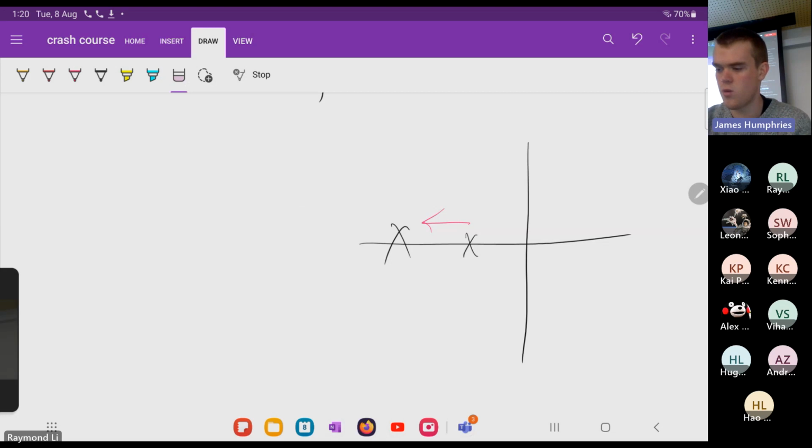Because if I go back to this, let's say I have a single pole. What happens as I increase the gain? It goes not to the right, it goes to the left. It'll go this way, and it'll eventually just keep going that way. Which is why, when we have two of them, we like to put the zero here, because then this one will go this way after this one gets there. They'll go that way for a bit, but it'll mainly end up going further to the left. Because we want to cancel out the dominant poles. We don't really want the dominant poles there, because they're too slow.